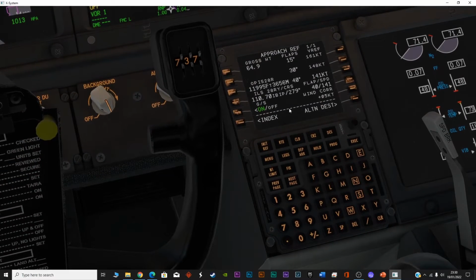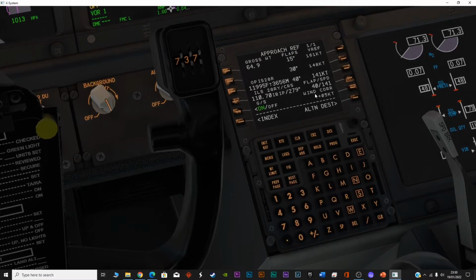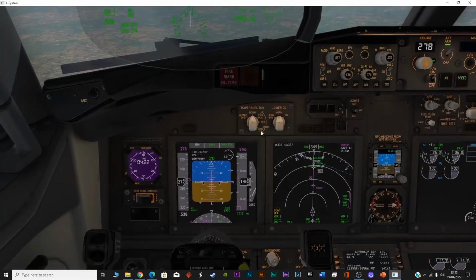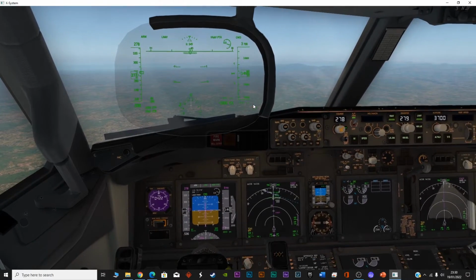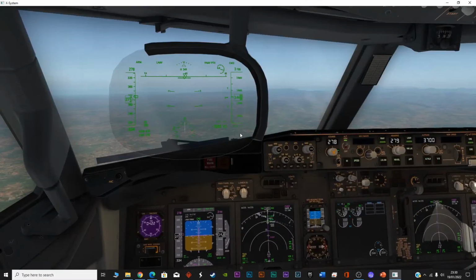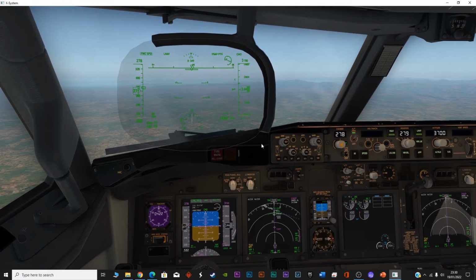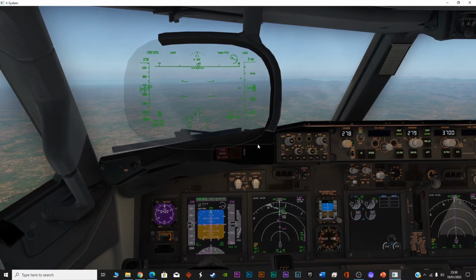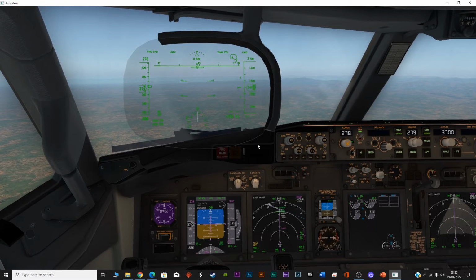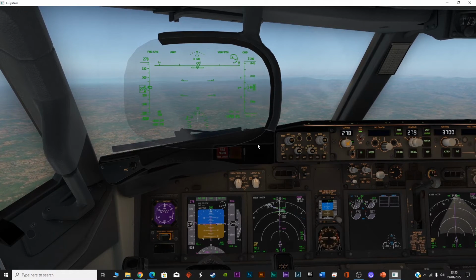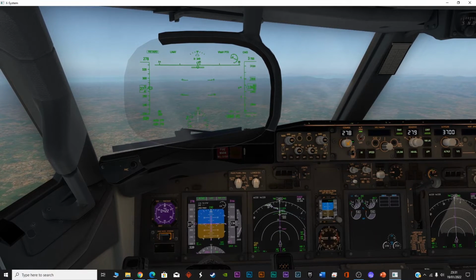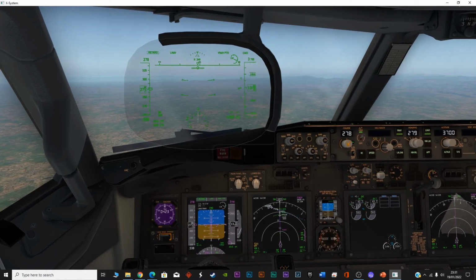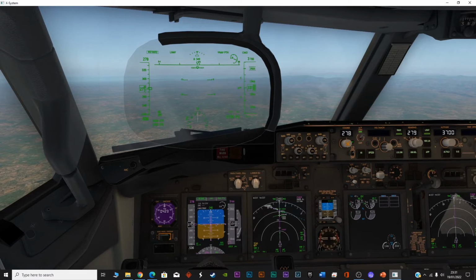As we are going for the full flap landing, the speed should be 140, which is easy to control. So I will start extending the flaps after the plane is below 10,000 feet, and the speed will start to reduce. We will hear some errors because right now the speed is getting adjusted by the autopilot, so we will ignore it, but eventually the speed will slow down. So after below 10,000 feet, I will go with 3 degrees of flaps, 3 notches rather, up to 5 degrees.